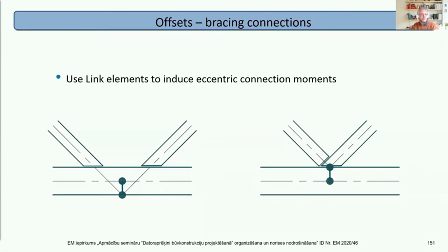As a rule of thumb, I might say if that dimension is twice that one, then maybe you could go over to having separate elements. There's no definite rule, but again, it's a question of sensitivity analysis. If you know you're in that border area, make the two models, even as an experiment, and see which one behaves more appropriately. So yeah, engineering's fuzzy.